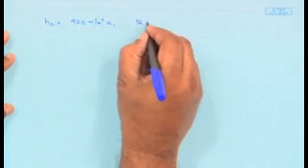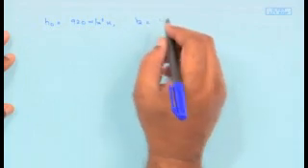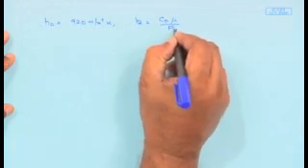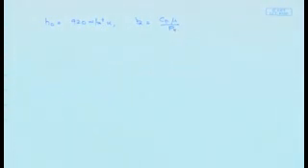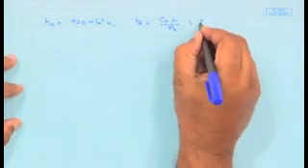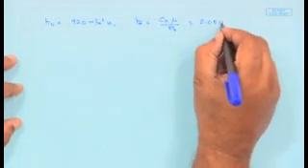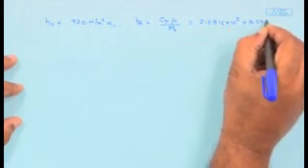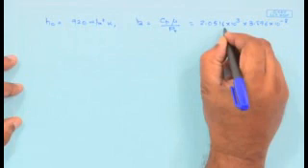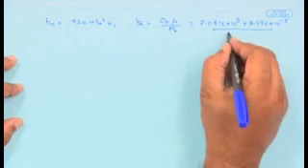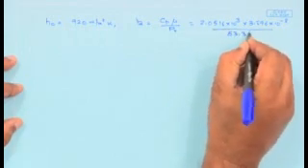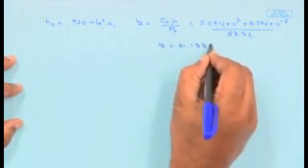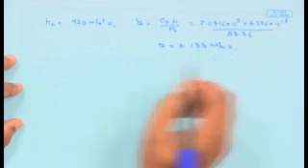The thermal conductivity k of the crude oil is obtained from the known value of the Prandtl number. Simply by putting in the values of Cp, mu and Prandtl number, one would be able to obtain k to be 0.133 watt per meter Kelvin.